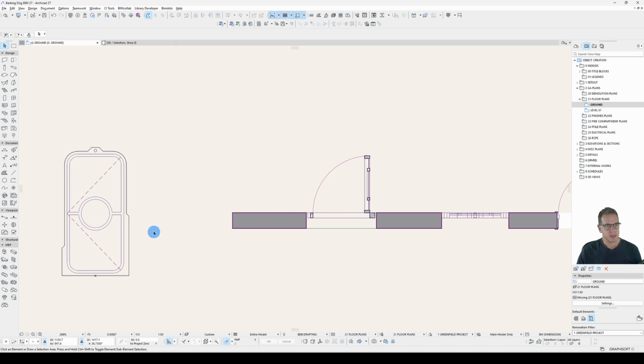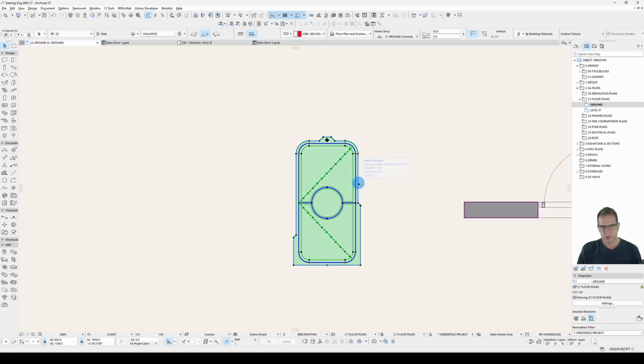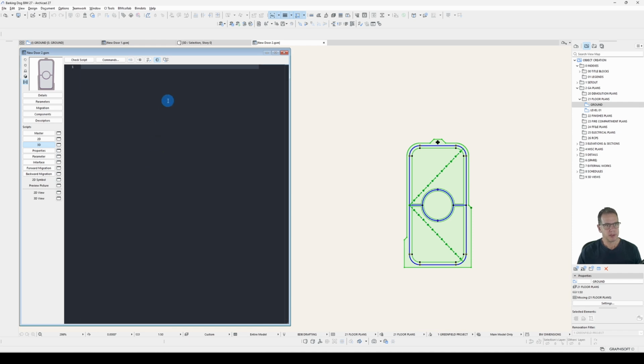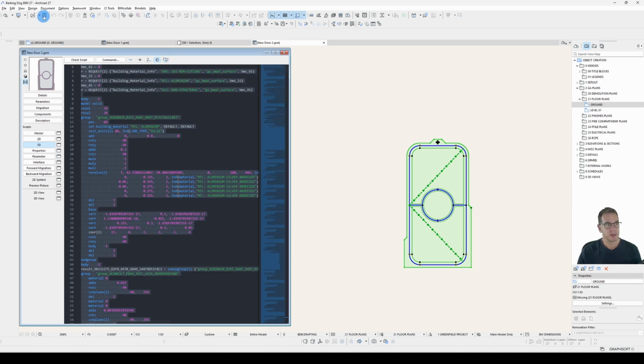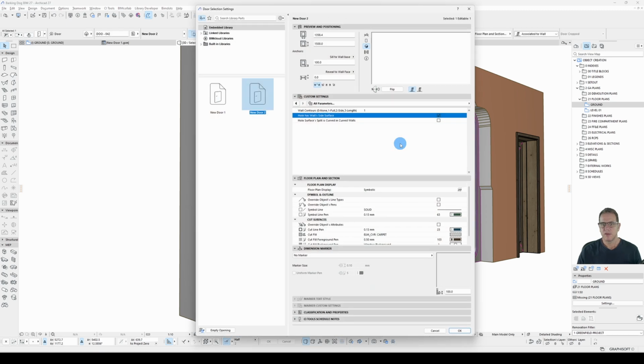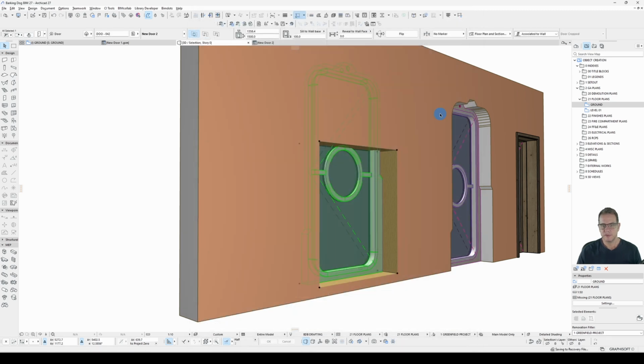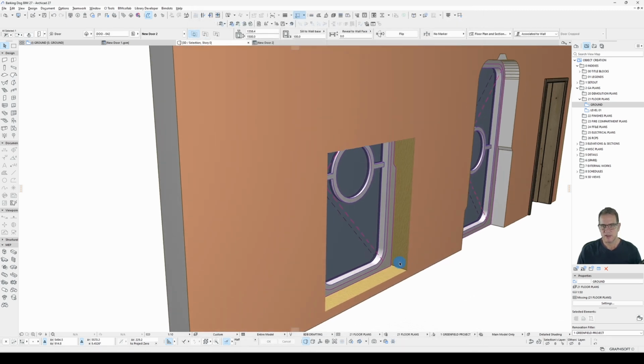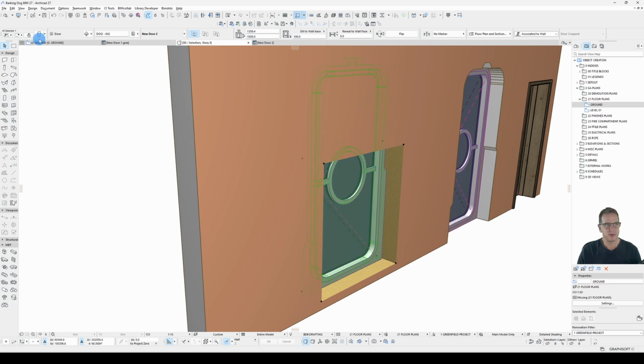So let's come back to here, select all my geometry, deselect my wall hole slab, and repeat the process of generating my script. Has no wall hole, so my wall hole won't be right. So that's inherited this side surface of my wall. If I turn it off, it goes to a different one altogether.